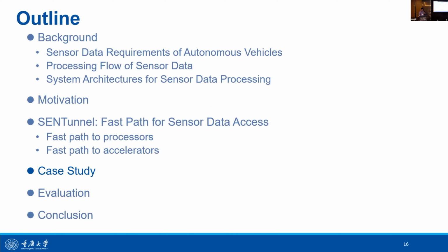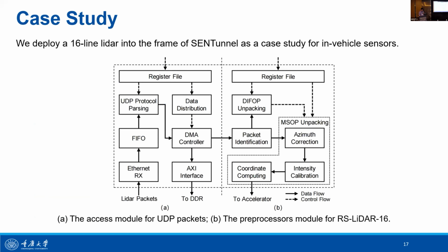We deploy a 16-line LiDAR into the framework of Centano as a case study for in-vehicle sensing. This LiDAR takes the UDP protocol as a data transmission protocol. We use FPGA to implement the unified access module and the preprocessor modules.